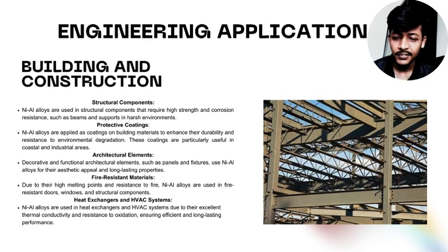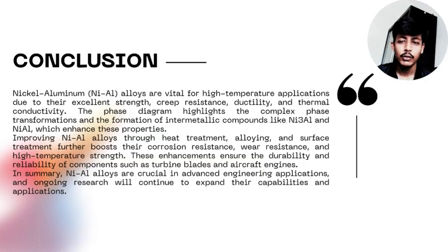And if we compare fire resistant materials, nickel aluminum alloy has a high melting point for fire resistant doors and windows. Also, we can see this alloy used in heat exchangers since it has efficient thermal conductivity. In conclusion, nickel aluminum alloys are indispensable for high temperature applications thanks to their superior strength, creep resistance, ductility, and thermal conductivity.